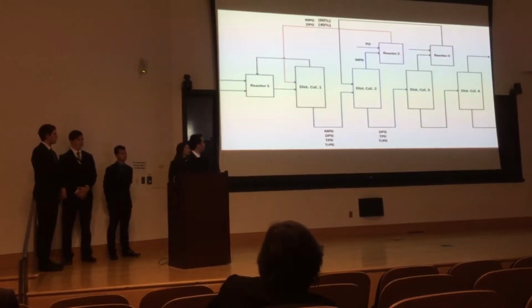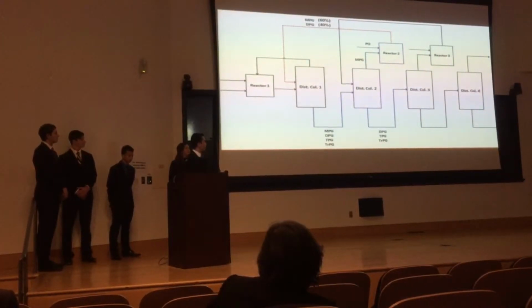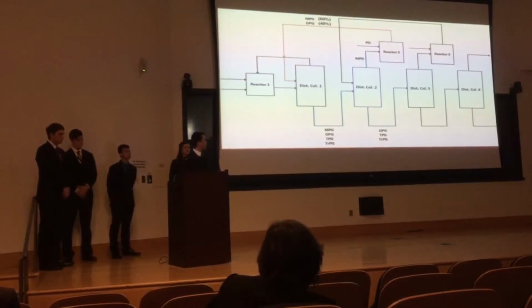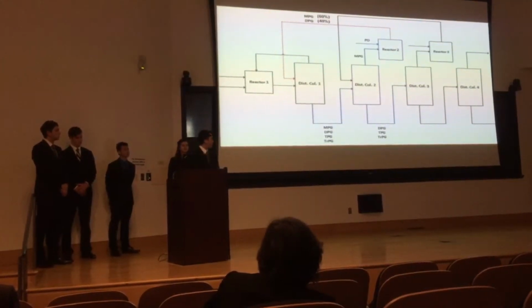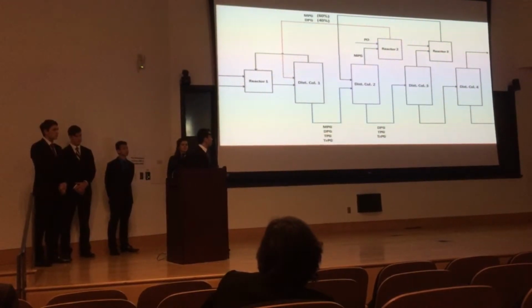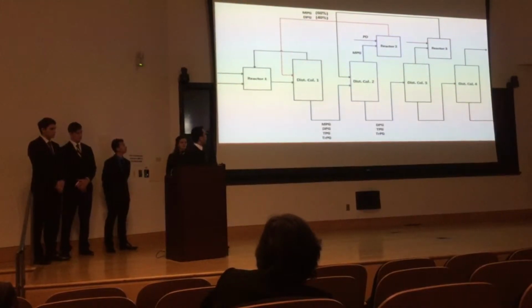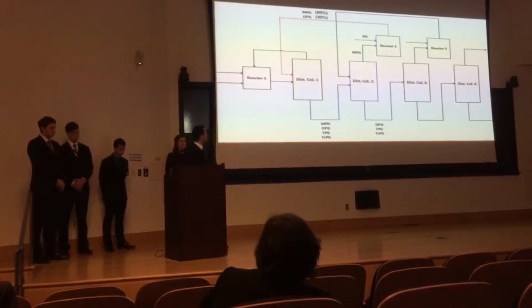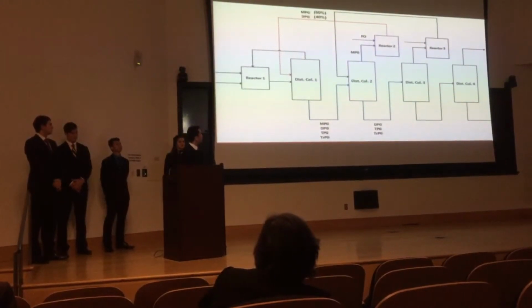As shown here, on the top of the column we separate monopropylene glycol and further react it with propylene oxide in plug flow reactor number 2. In order to minimize tetrapropylene glycol, we want to control the ratio between propylene oxide and monopropylene glycol. We found that we can convert 40% of monopropylene glycol to dipropylene glycol, leaving 60% of the monopropylene glycol unreacted.